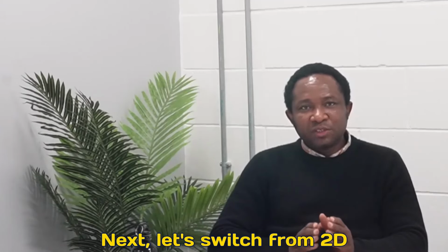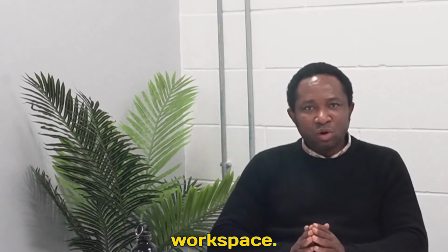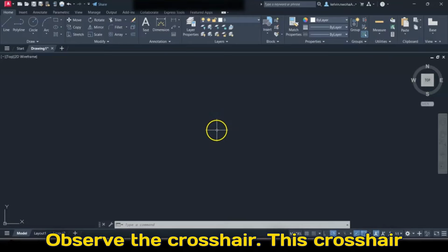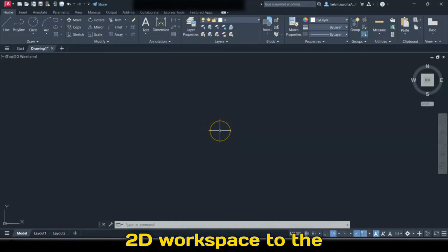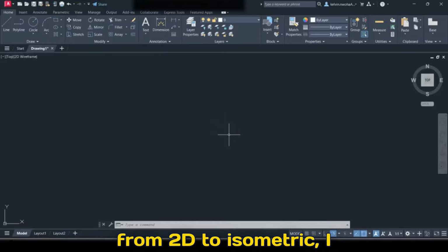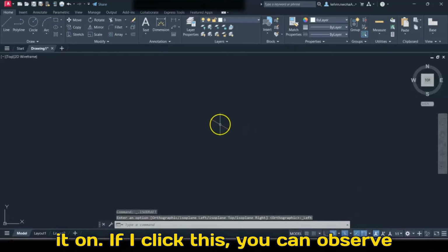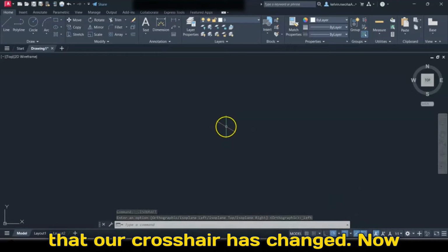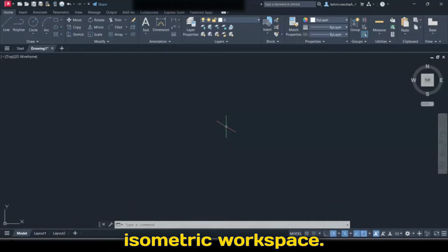Next, let's switch from 2D workspace to isometric workspace. Observe the crosshair. This crosshair will change when I switch from 2D workspace to the isometric workspace. To switch from 2D to isometric, I will click this ISO draft by turning it on. If I click this, you can observe that our crosshair has changed. Now we are ready to work in the isometric workspace.